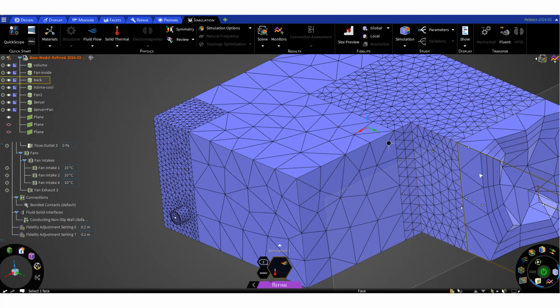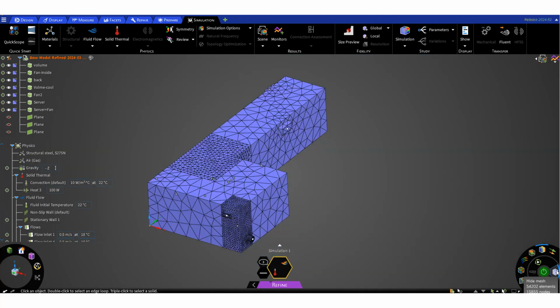So basically we refine the mesh in this area, but on the other part of the domain next to that we don't have such local refinement, and that's why you see a much larger size for the triangular and tetrahedral elements here. The number of elements from the very low fidelity that we had used to be something like about, okay, let me share it here.